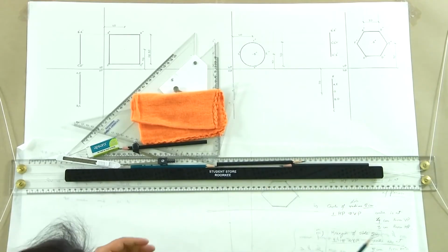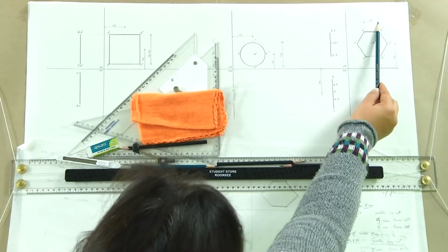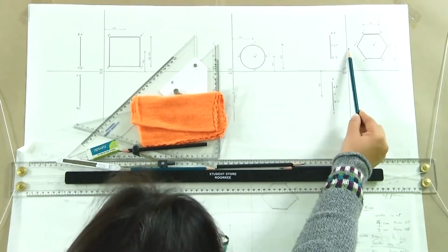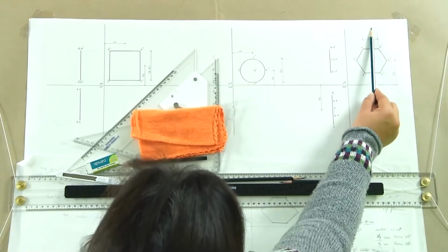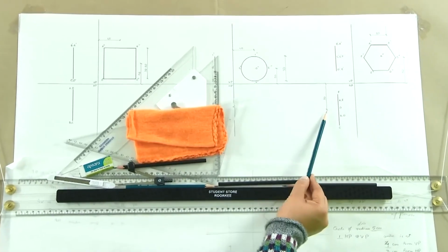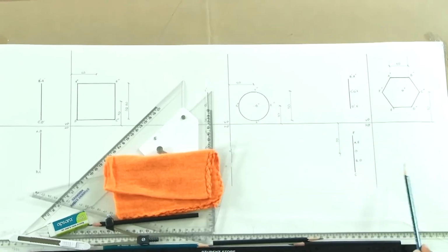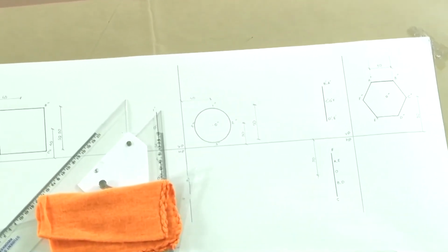Now, when I started to dimension, I have the hexagon of side 3 centimeter. So, I have given hexagon of side 30 mm here, and then 50 mm from HP and 50 from VP. Now, if I were to take 50 from VP here, this dimension line would be intersected by a projection line. So, I prefer to represent this distance from VP here in HP, and this is what your final solution would be. I am hoping that all of you have got a similar solution, and if not, you can watch it again and see what are the steps to be followed and where did you go wrong.